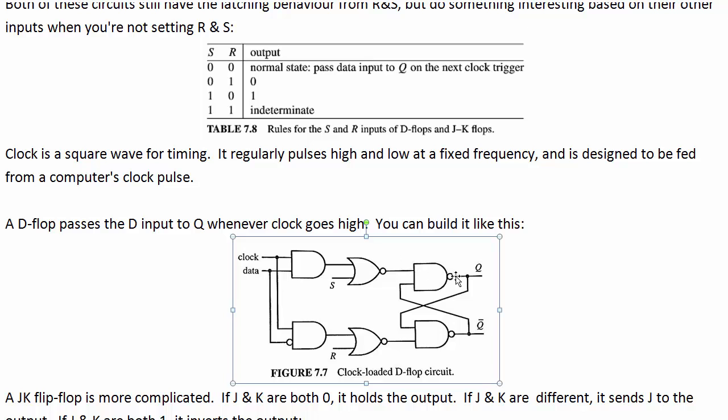Right? If one of these goes to low, then this goes to 1 from whatever it was at. Conversely, if we get a 0 here, either because we put the reset pin to a 1, or because clock went high when data was low, then we put this to a 0, and that puts the output Q bar to a high, which conversely puts Q to a low.